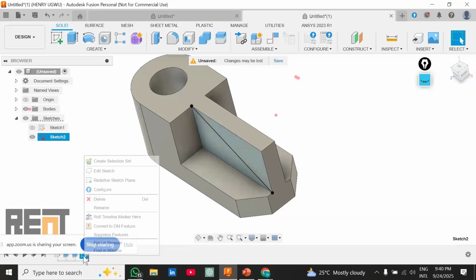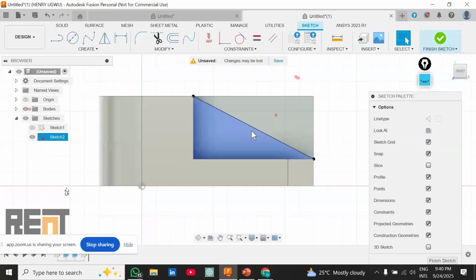In some cases, by dividing this face or this surface into two separate surfaces with this line, and you are trying to select any of the surfaces to extrude, in your own case it might not work depending on the model you are designing, not this exact model. In the future when you end up with this error, what you have to do is to complete the profile. Okay, you just do a complete profile. Understand? Do a complete profile.